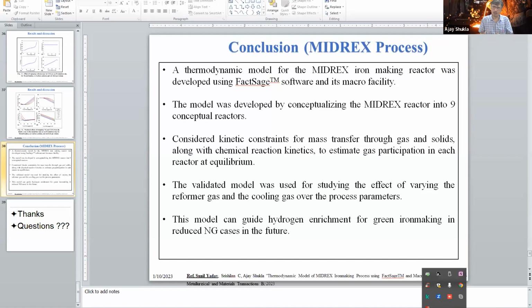Secondly, if you are talking about the liquid medium where the slag-metal reactions are taking place, the process may be very close to equilibrium, where there is very efficient mixing. For example, in oxygen steelmaking, thermodynamic equilibrium may be very close in the hot spot zone, or the regions which are receiving more mixing energy, particularly the middle part of the process where there is an extreme level of turbulence in the reactor. The behavior of the reactor may be very close to a fully mixed reactor, and the entire reactor may be very close to equilibrium for the time when there is a lot of turbulence and mixing.